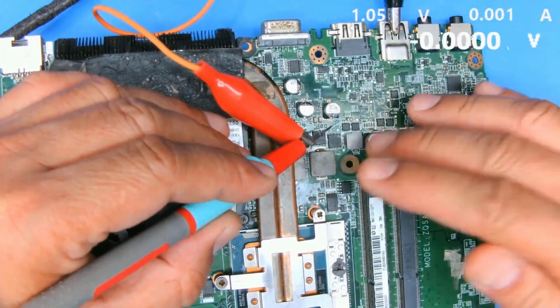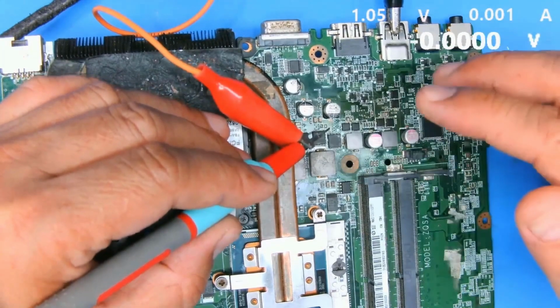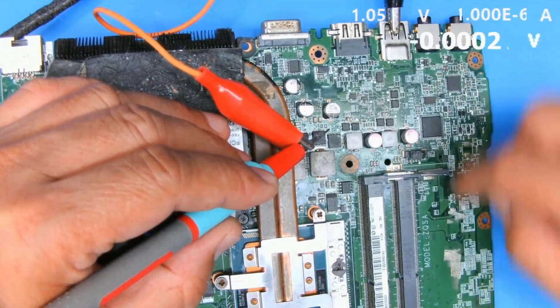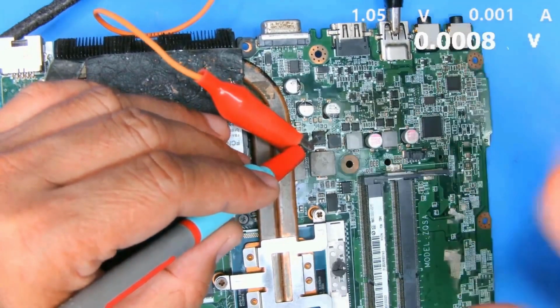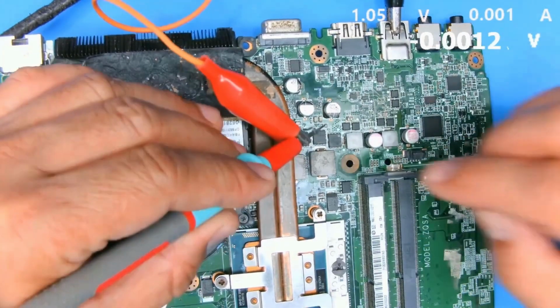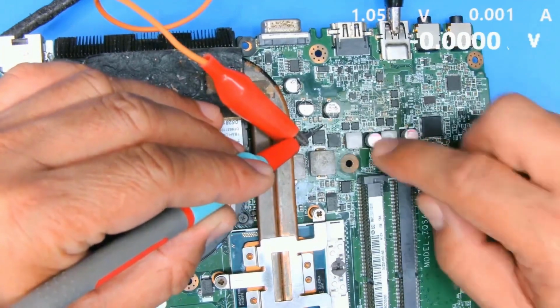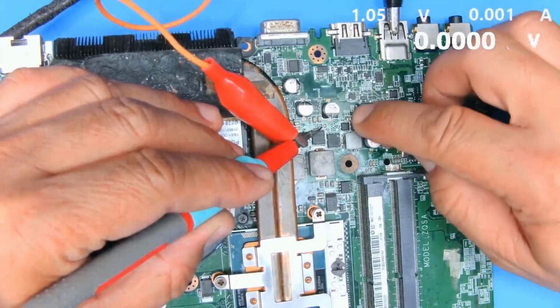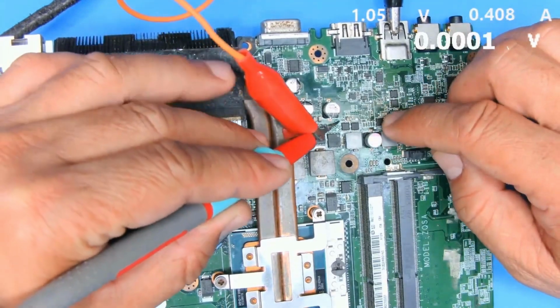For this, I can probe any of the 49 points, because when it shorts, this one shorts, all the others short as well. When the others short, the meter doesn't tell you which component is faulty. It only tells you the faulty group, so we still have to find the faulty component ourselves because of the supply. First, use the meter to check in a cold state, meaning without plugging it in. Use the diode mode to check. If it's shorted, then we inject power.